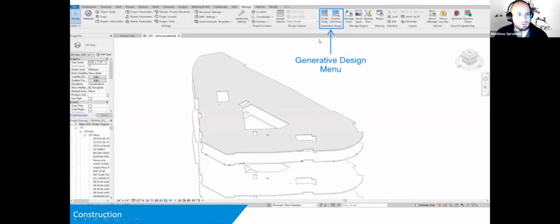So in this case, this is using Revit 2021, and you can see that now you can access generative design right inside of Revit. So you don't even need to use Dynamo if you have a simple program. In this case, they broke the tower down into the profile, and they were able to see what the supporting buttresses of the concrete should look like. And they needed to know, if they're going to 3D print this formwork, what is the optimal geometry that this formwork should be laid out as.